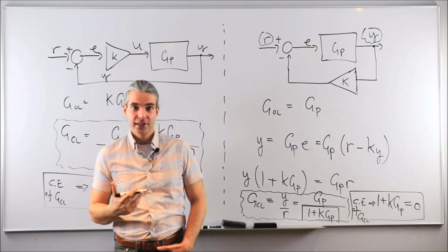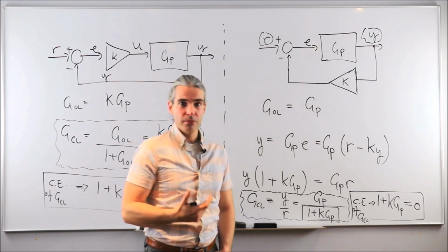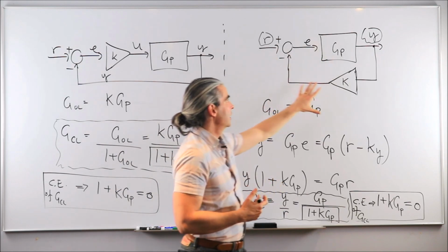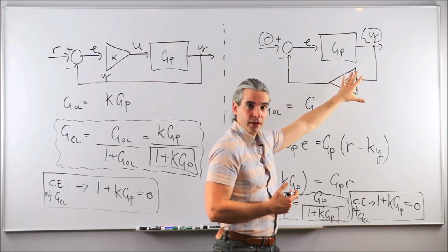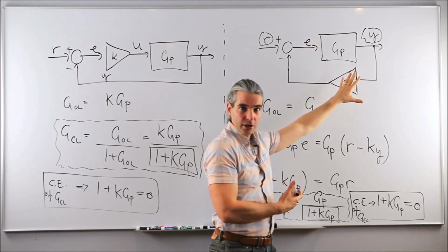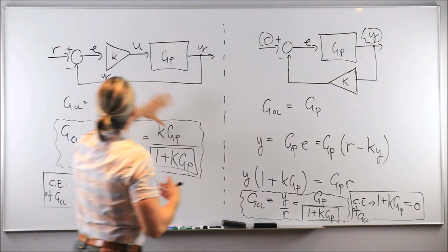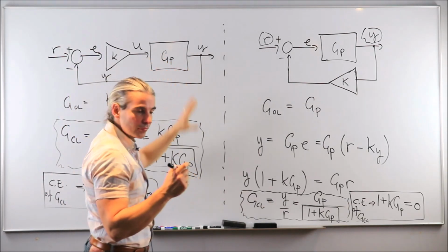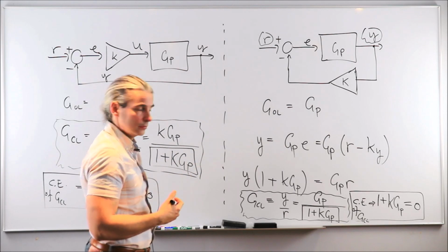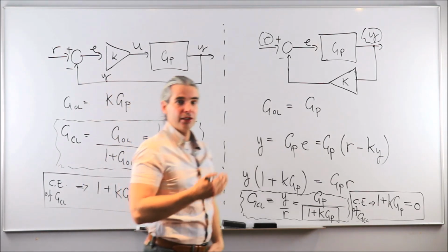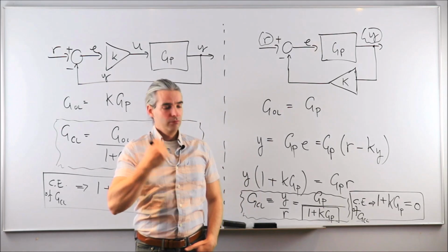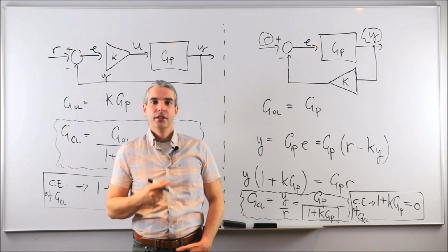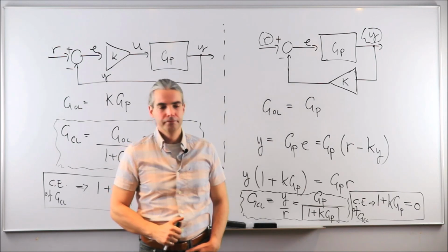So the answer is yes. We can confidently use the MATLAB rlocus function, even though the built-in architecture that MATLAB assumes whenever we type rlocus is different than what we had used so far in terms of constructing the root locus manually by going through the 9 rules. All right, good news. So let's go back to the computer and let MATLAB do the root locus for us by using the rlocus command. Let's do that together.